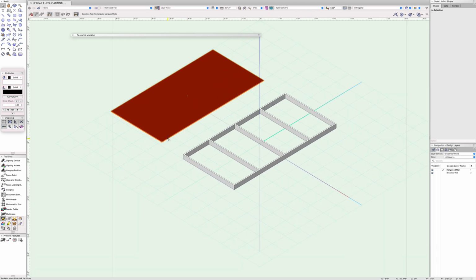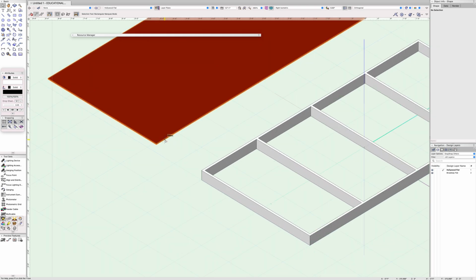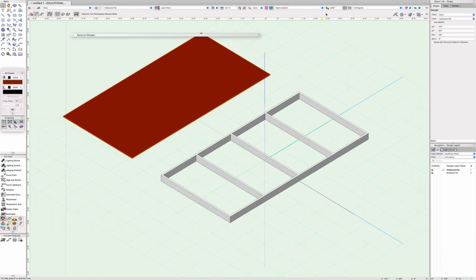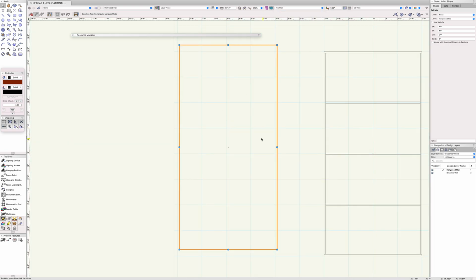Now the next thing I want to do is to place this luan on top of this frame. Now remember, the luan has also started from the 0 plane. So if you select the luan and look into the extrusion object info palette, you see the Z axis starting point for this luan is 0, because this frame is also 0. So we want to start the frame from the 0 plane on the Z axis, but we want to put the luan on the top of this frame. One way to do that is to go to the top plane, drag this.